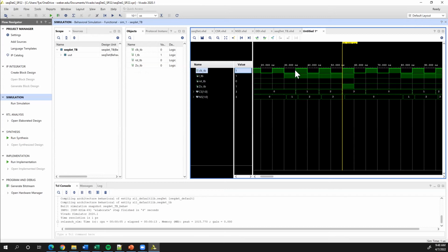However, then I clock it in and I go. So this state machine is a little bit odd in its behavior, I guess, in that kind of edge case. State 1. That takes us to state 2. That takes us to state 3. And then because our next state at that point is 3, goes to 3, and then we go back to 0.